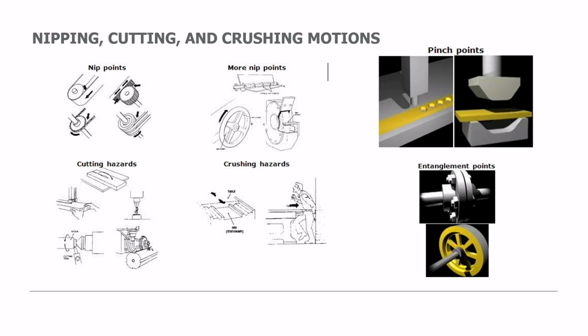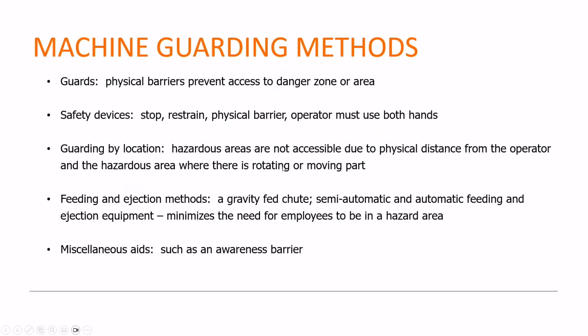As far as wherever it's going to cut. And then, of course, you got what they call crushing hazards. Remember, crushing hazards is going to be something that's going to be pushing against the body, and usually it's going to be a solid surface directly behind that person's body as well. Basically, the individual becomes sandwiched between the crushing hazard and the wall itself or the machinery, and that is where a person will actually have some issues.